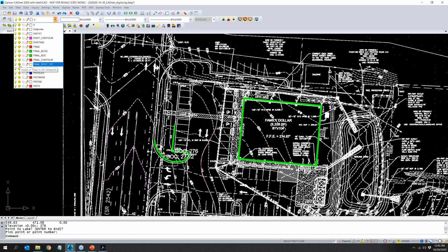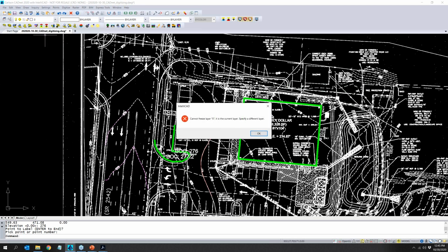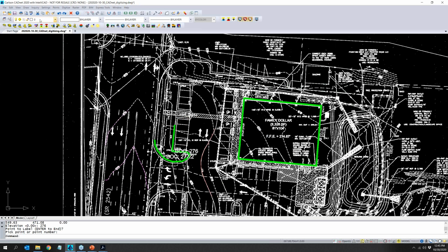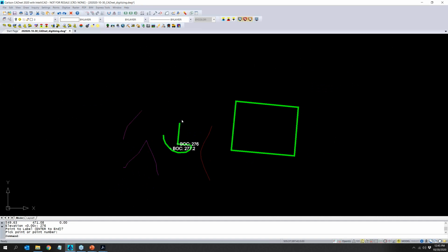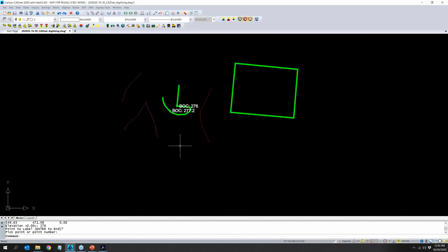And I was going to freeze my image. I guess it's on that. Yep, there we go. So that's what I'm left with, okay? So I have some contours that have elevation, and then I'm going to end up with polylines for back curb, buildings, things like that, that don't. So I'm going to have to use the software some other way in order to elevate all this stuff.